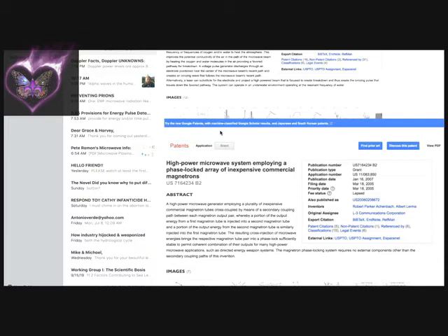The result, cross-injection of microwave energies, brings the respective magnetron tube pair into a phase lock sufficiently stable to permit coherent combination of their outputs for many high-power microwave applications such as directed energy weapon systems. The magnetron phase lock system requires no external components other than the secondary coupling paths of this invention.